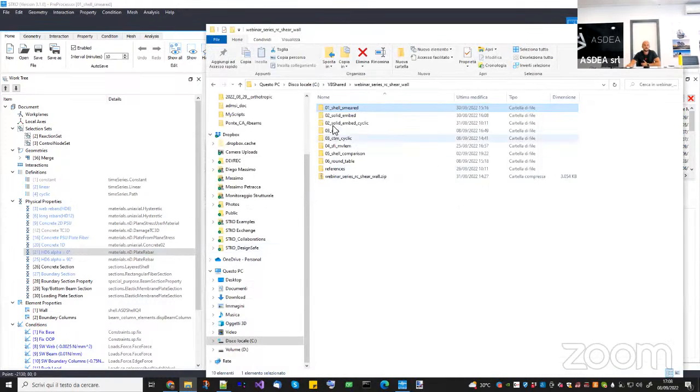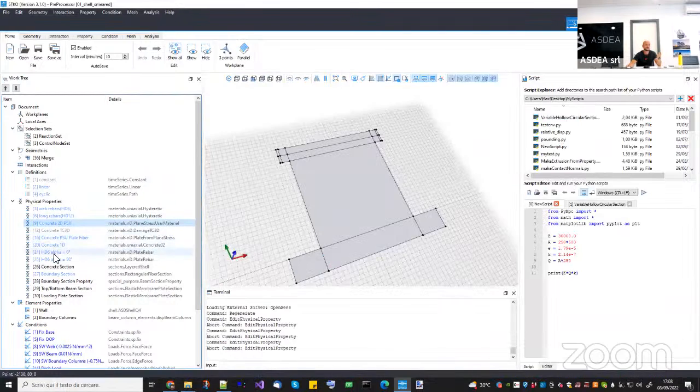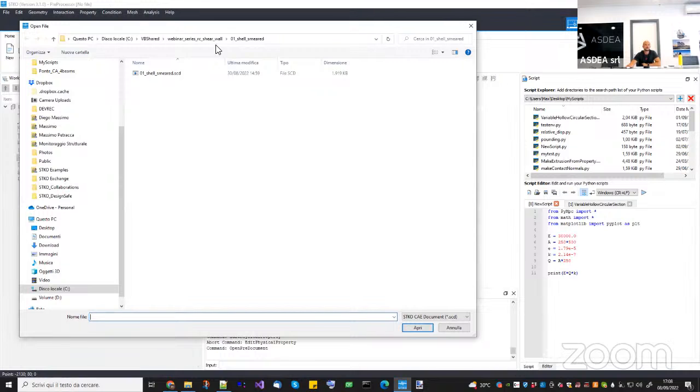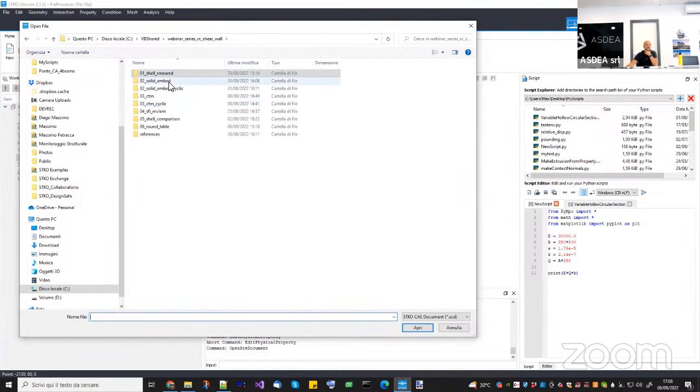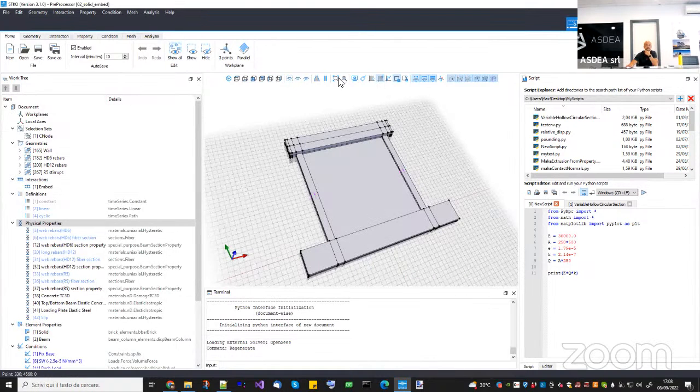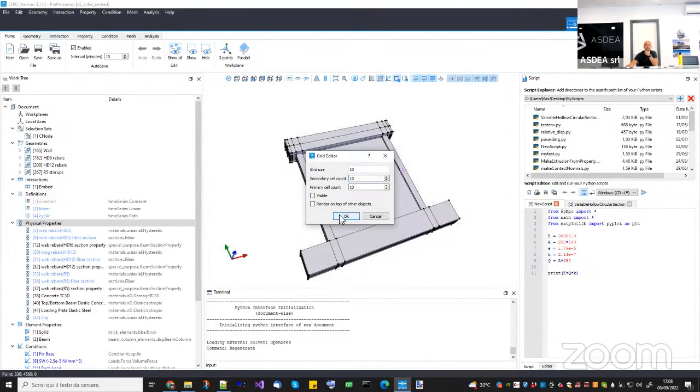Then in the second lesson, we have seen how to use solid elements, but it was not actually focusing on solid modeling itself, but on how to use embedded rebars. For example, in a solid element, you cannot use the concept of smearing the rebars with the plate rebar, because this is done for shells. Instead, with the solid, one option that you have, if you need to do detailed solid modeling, is to use the embedded approach. Just a brief recap to explain what it is.